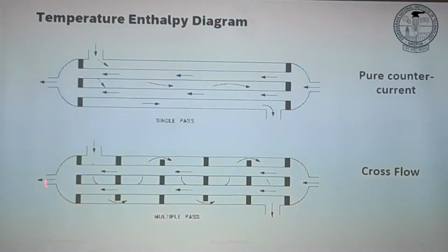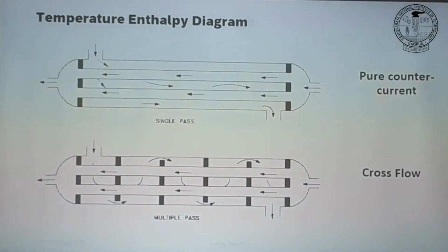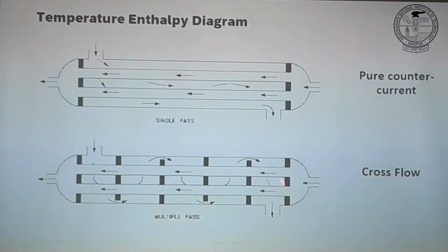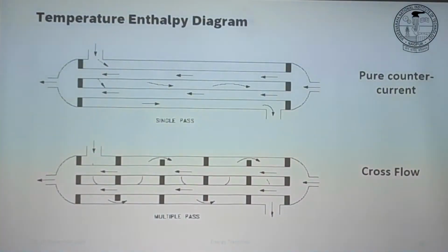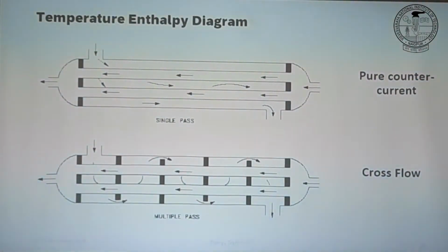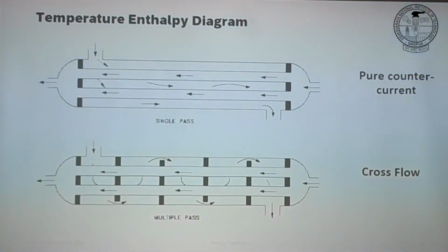But while doing this, you drastically increase your Reynolds number because you enhance turbulence. If your Reynolds number is higher, maybe you can reduce the size of the cylinder because your H is higher. H is higher, U is higher. U is higher, your area is higher. So once again, you see how this small equation is dictating your CAPEX OPEX optimization.